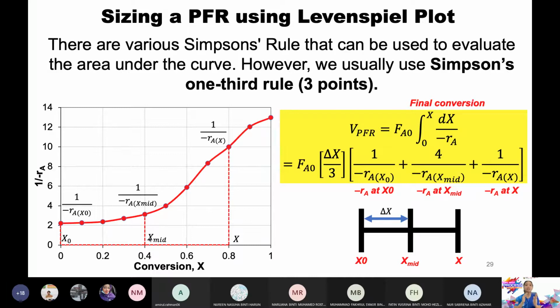Actually, if you ask me, the bigger the rule, meaning 5/7, 7/12, the calculations are more accurate, because the more you split the area into smaller parts, the calculation is more accurate. If we use 1/3, not so accurate, but it's okay. So Simpson 1/3 rule is sufficient enough to know the volume. Maybe if you ask, is it accurate? In terms of reaction, the difference in volume between 1/3, 5/7, 7/12 is not significant. So it's fine to just use the 1/3 rule.